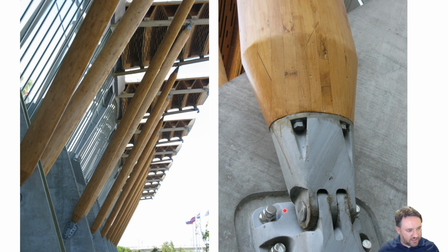You can see the pin here, using lag bolts, which are threaded through at the end of the member. So basically we're penetrating into the end grain of the member here. So it's nice. It looks pretty hidden. So we couldn't do this with a bolt, obviously, because where would we put the nut, right? So screw is one way to do this.